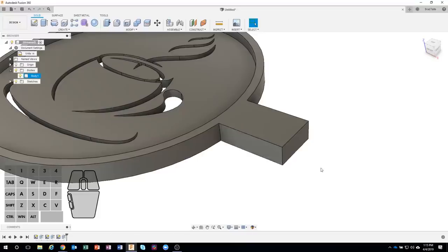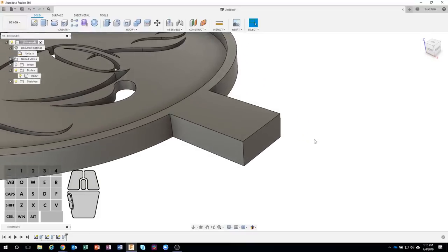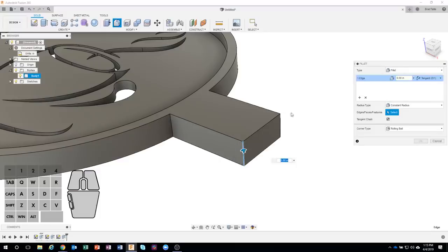Now the last thing I want to do is round over these corners. I'm going to show you another little tip here that I think is kind of useful. I want to fillet this edge, so I'm going to select it and then right mouse click and say fillet. Now let's pretend I forgot what the width of this rectangle is. I didn't write it down on a post-it note or whatever. Maybe it's some weird number like 0.713 or something like that. Well, I want to make this go half the length of whatever this edge is. So I can come in here and say measure.